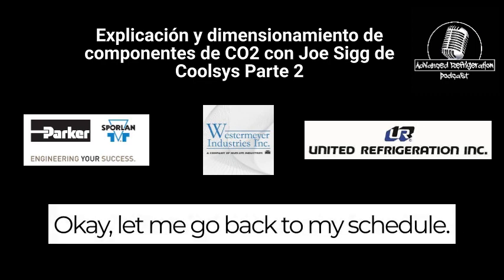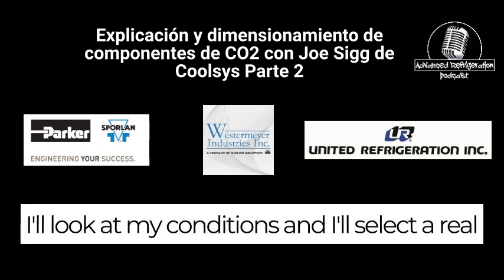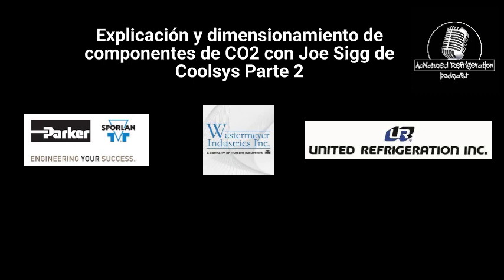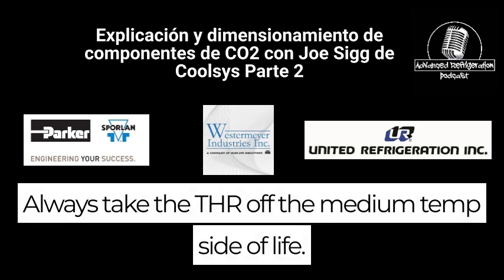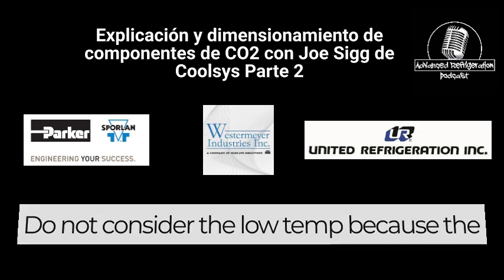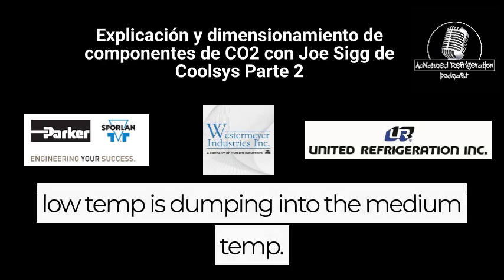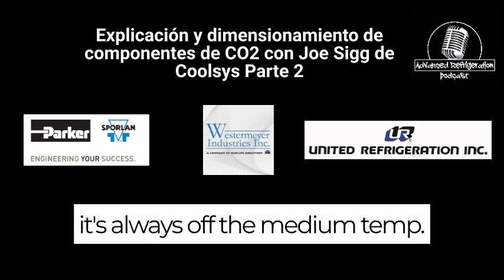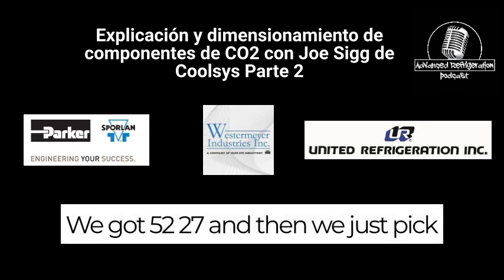Let me go back to my schedule. I'll look at my conditions and I'll select a real world adiabatic gas cooler for this system. You always take the THR off the medium temp side. Do not consider the low temp because the low temp is dumping into the medium temp. So when you get your THR, it's always off the medium temp. We got 5227.